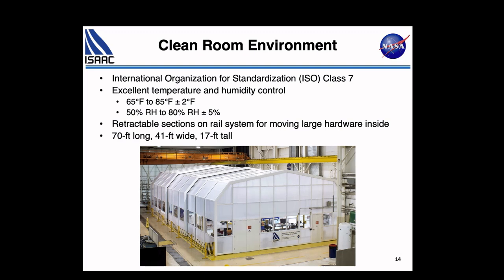The epoxy system we work with is sensitive to temperature and humidity, and we want to be able to build the same part in January and July. Therefore we got the enclosure so that we can have our own temperature and humidity control system, and we don't have to worry about what's going on elsewhere in the lab.